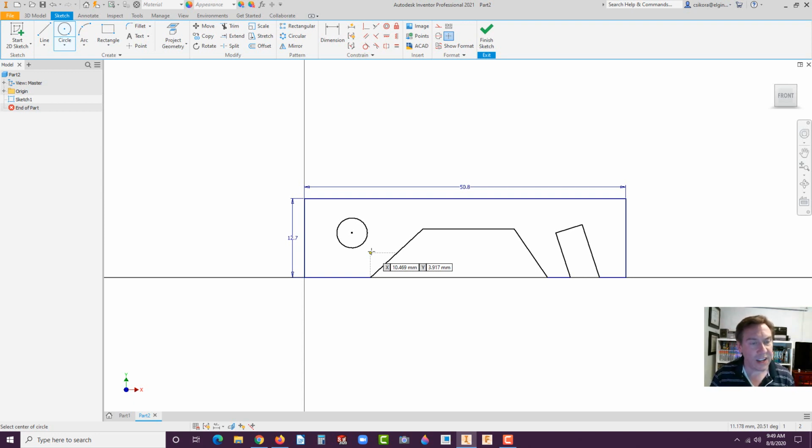And linear analysis is desirable for simple parts such as this. Other parts, not so much. You might want what's called nonlinear, and that's an advanced stage we're not going to cover today. But anyhow, let's go ahead. We're not going to put the fillets in because they're just not really necessary all the time. If it is a structural fillet, then yeah, but we don't really need it on this one.